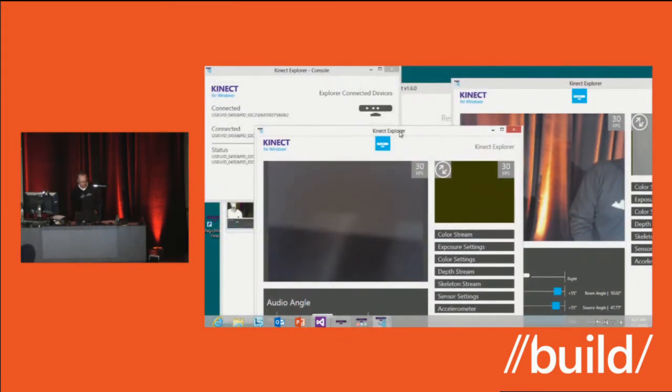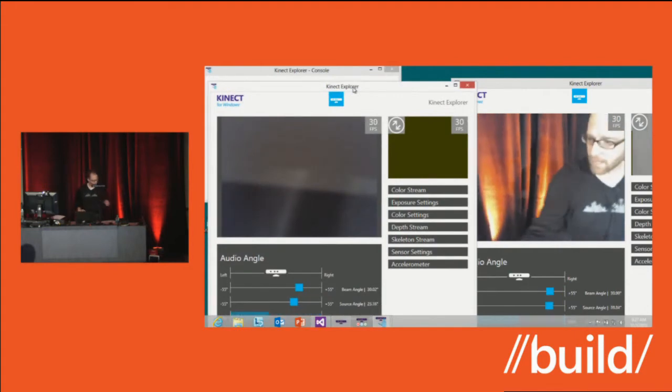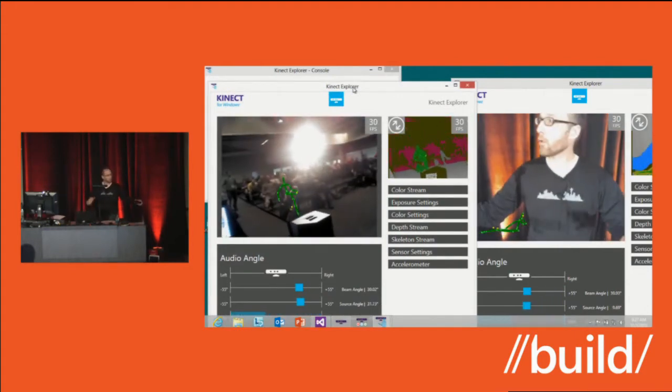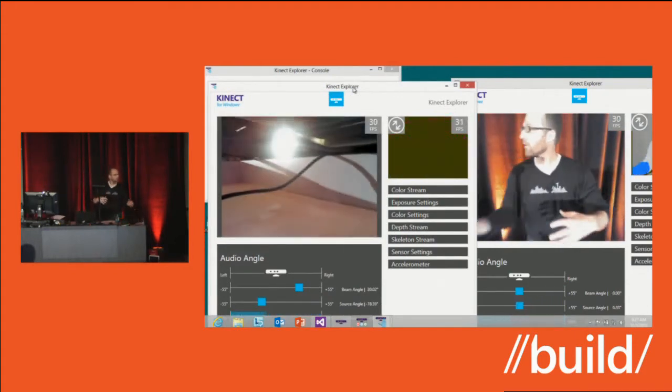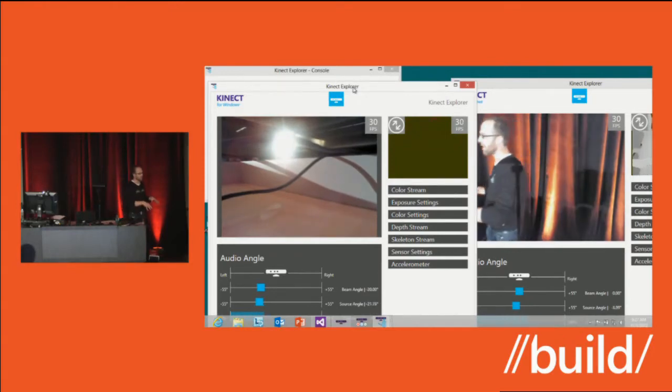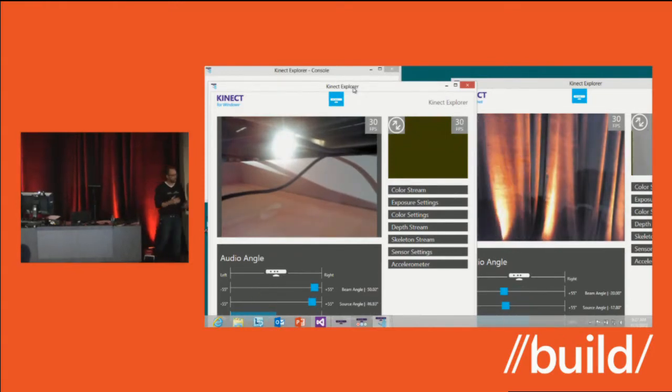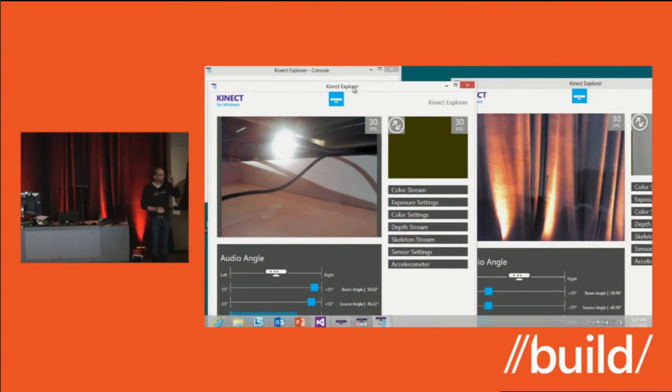We've got both sensors, and we're getting color, we're getting depth from both of those sensors into one app. We support up to 4 sensors into one application, probably more than that. You need 1 USB controller per sensor that you have. And it's definitely an area that's interesting to figure out how can I have 4 of these in a room and 3 of these in a room and triangulate, etc.